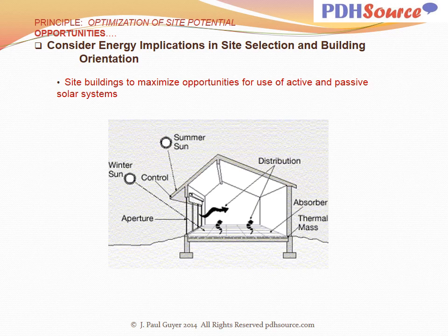South-facing apertures, windows that is, typically some kind of shading mechanism so that you can shade those south-facing windows in the summer, but have the sunlight pass through those apertures unimpeded in the winter. And then thermal mass and some other features.